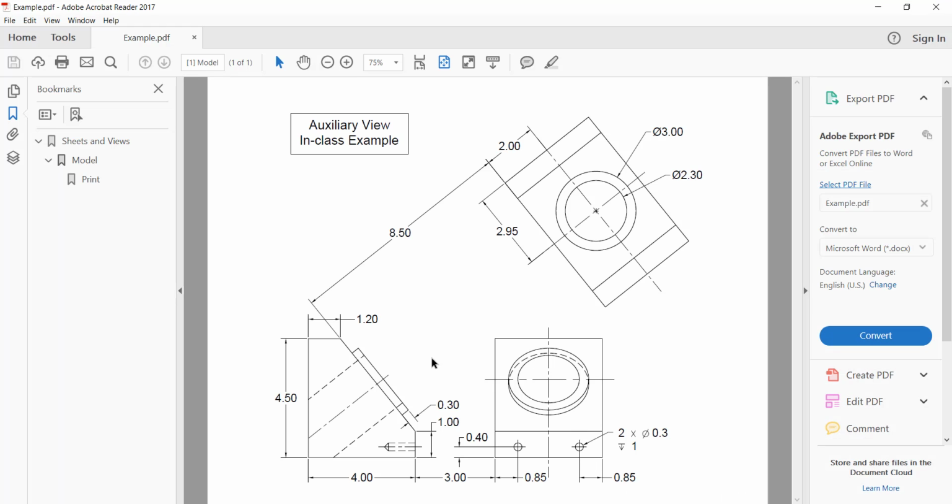And after that, we're going to project this part to the right and draw these two ellipses. So on the right side view, this point is the top point here. And for the smaller ellipse, it's these two hidden lines. So that's the smaller ellipse. And the hidden one in the back is representing this point. So this point should line up with this one. And the bottom one is the bottom one here.